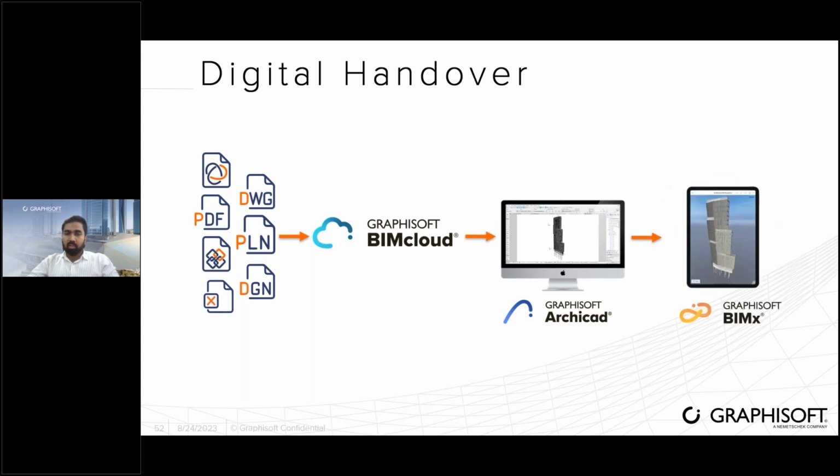But if you publish it as BIMx file format, especially when it is on the cloud, you can load this model from the BIMx model transfer site, and then we can send across messages to the project stakeholders who are joining the project. This way we have a live model or the live document of this BIMx file, which is available throughout the facility management stage after you have the as-built model created inside Archicad.